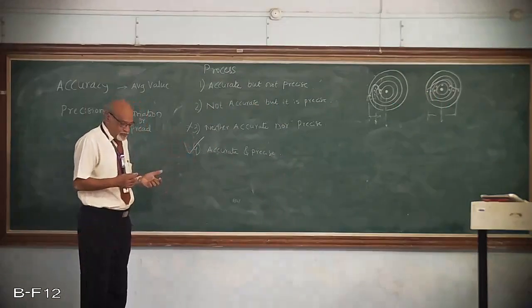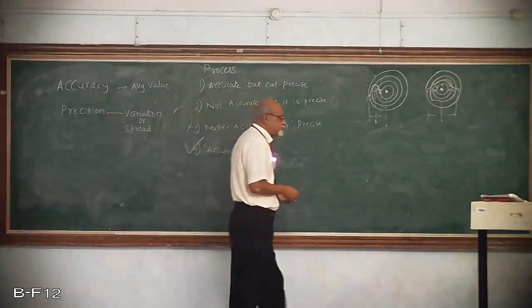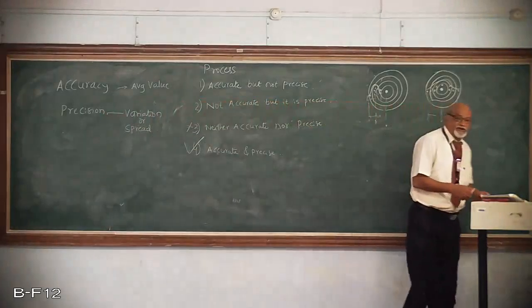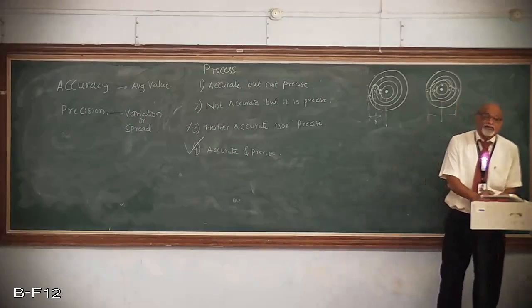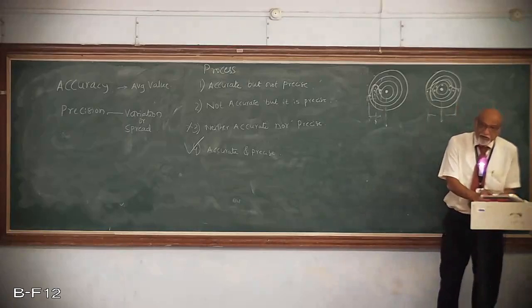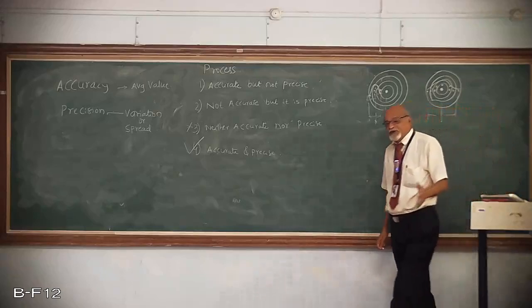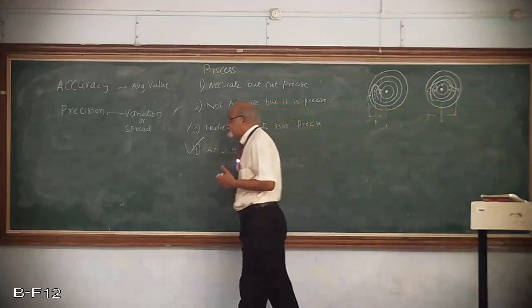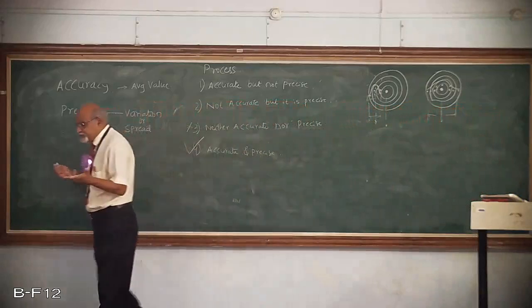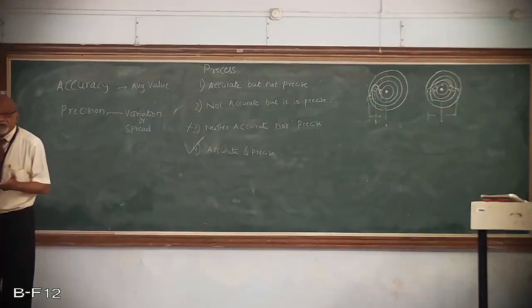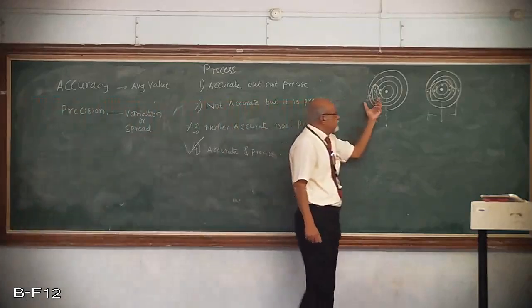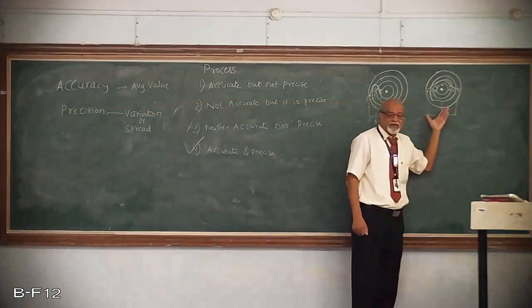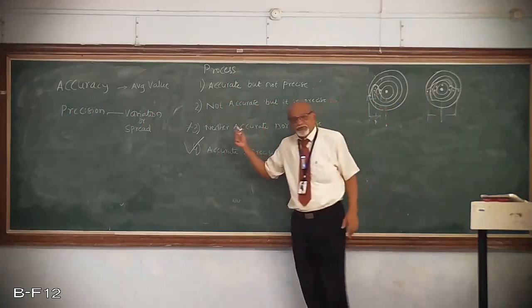So we learn from this what is meant by precise and what is meant by accuracy. Mostly in SQC, statistical quality control, precision is inbuilt, that is what we accept. Variability is going to be there. We cannot improve upon it. The variability for this person is so much, and it is going to remain there. That is what we assume in this case.